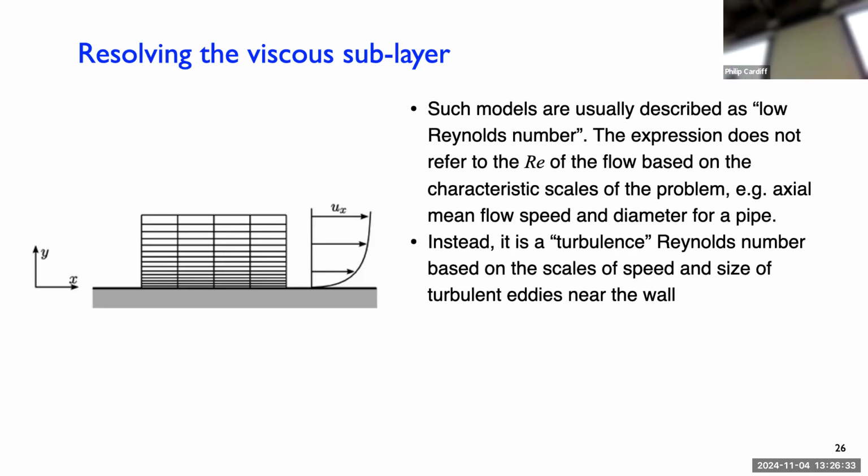But if you are resolving very close to the wall, then the turbulence model you're using, and we talked about k-epsilon, has to be well suited to that. The turbulence model has to be able to predict the turbulence right up close to the wall. The laminar region has no turbulence, but coming up to that, if you just use normal k-epsilon, it will probably predict turbulence in that laminar region when it shouldn't, because it wasn't designed for that. It's designed to work only with fully turbulent flows.